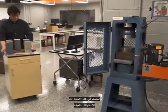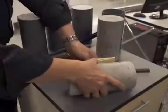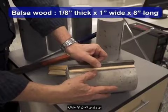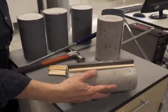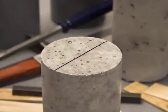For these tests, use the sample cylinders that were prepared in our video discussing fresh concrete. Use a thin strip of balsa wood and a stiff steel bar to help distribute the loads uniformly from the cylindrical loading heads in the compression testing machine. Draw a line along the diameter on each end of the specimen bisecting the cylinder.